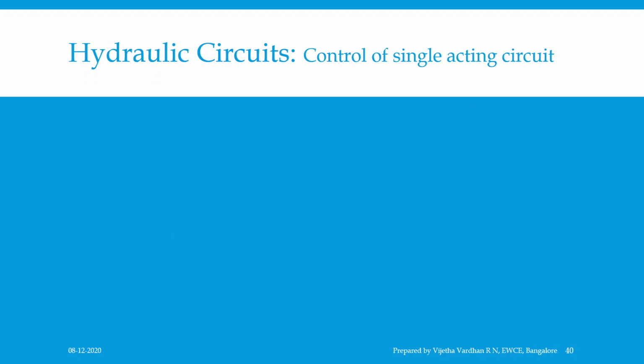Now let us discuss what is called a hydraulic circuit first. All hydraulic circuits start with a job to be carried out. The job may include lifting of load, pulling or pushing of load, rotation of tool, clamping and declamping of jobs, etc. Therefore, the design of a hydraulic circuit starts with the selection of the actuator followed by other elements and devices.